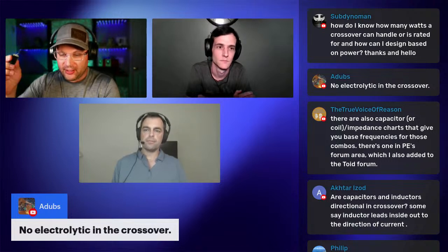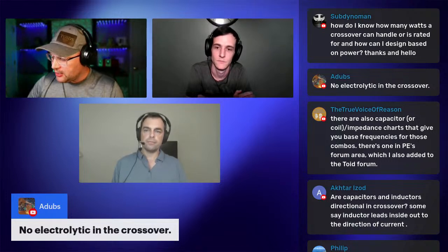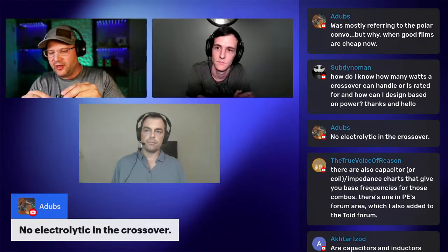Yeah, one thing real quick, that's a good point. If you look at the capacitors, you're not going to be able to see this on this particular capacitor, but it says brand Dayton Audio, 4.7 uF, 250 volts, and then this one says 1%, which means it should deviate about 1% of whatever its value is, 4.7. Now this one over here, for example, says 5%. There's some that will say 10%. You obviously pay more for the 1% than the 5%.